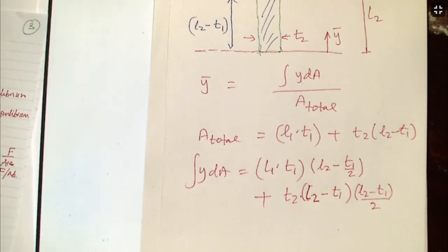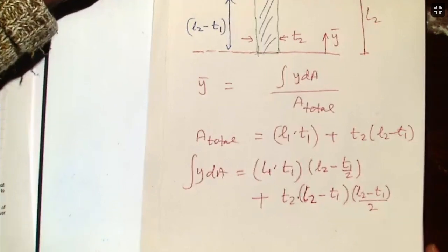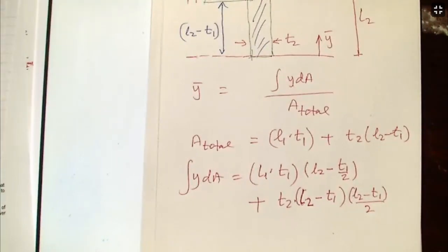I want to go back to the note now, quickly finish and do the two basic examples that we've got. Clear? So in order to find the bending stress, therefore, we need to know what is the bending moment at the point that we want to find the value of the bending stress. And we need to know how far we are from the neutral axis, which is our Y, to be able to find that. So if you are on the positive side, then it will be tensile. If you are on the compression side, it will be in compression.